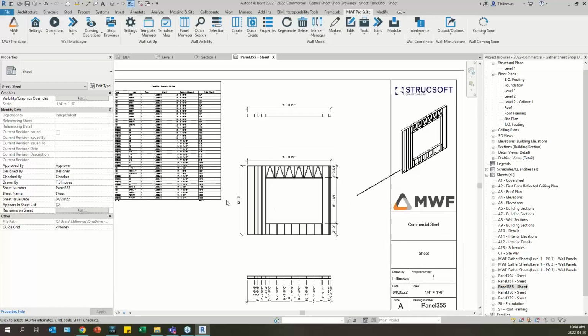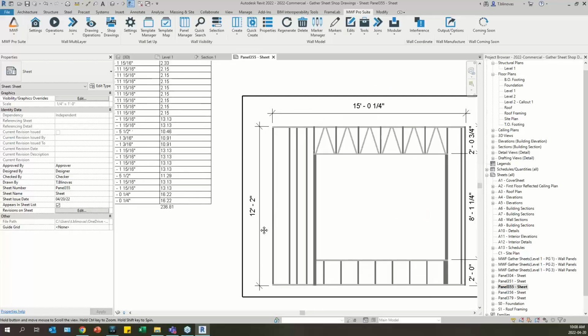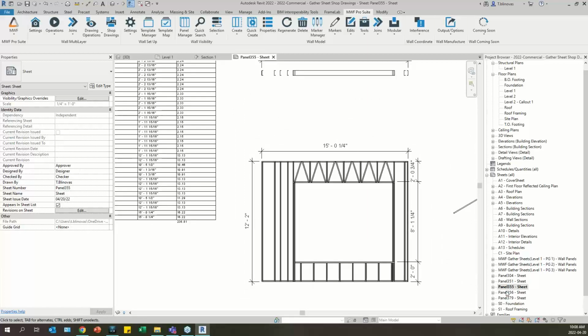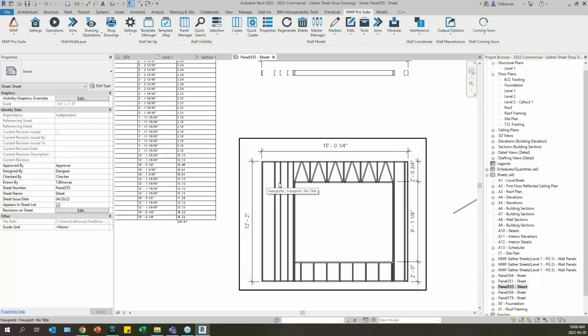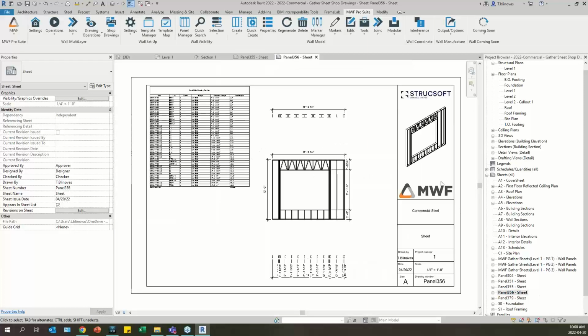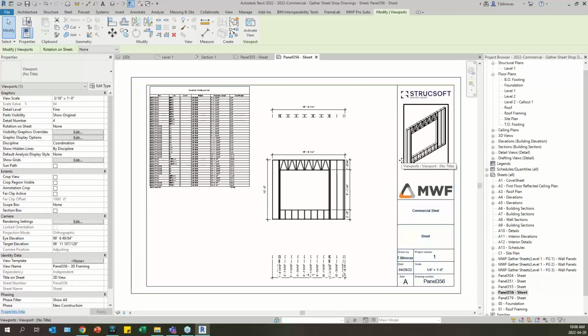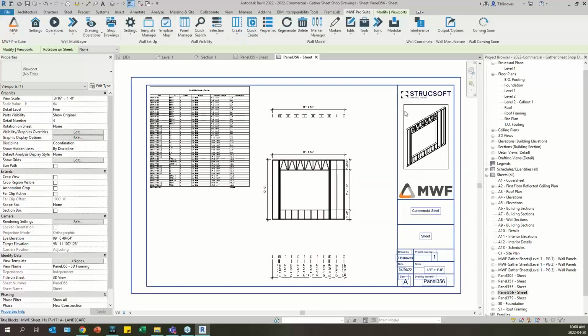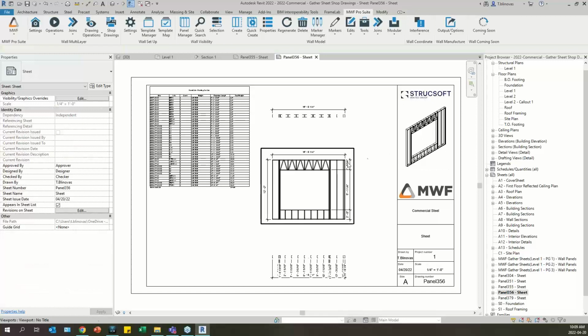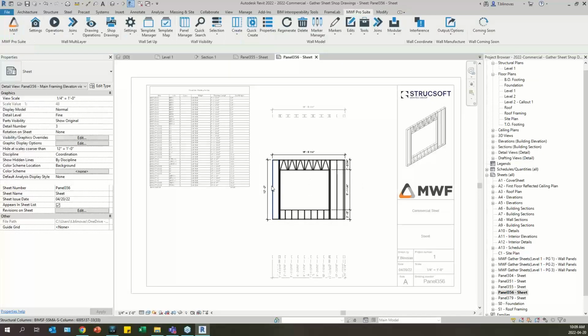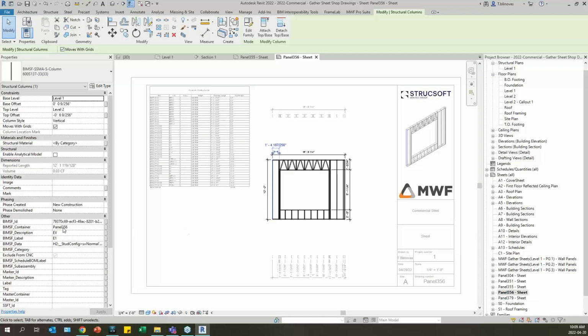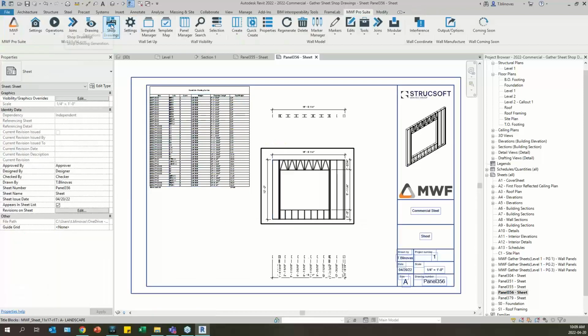The other situation where you could also use that option is, for example, if you regenerate a panel next to this one, sometimes this will cause some issues with the 3D view. So in case you are seeing extra elements in your 3D view, if you refresh the drawing, it should also revert back to the regular view. But again, this will only work if you didn't regenerate that panel specifically. So if I did make changes to this panel, my panel 356, if I regenerated the panel in any way, then I have to just rerun shop drawings again.